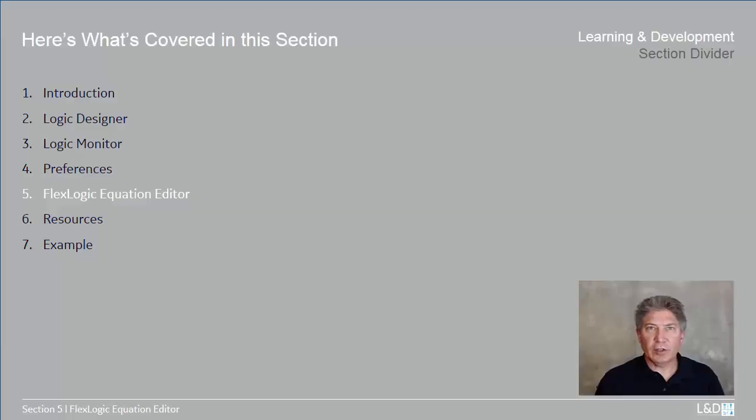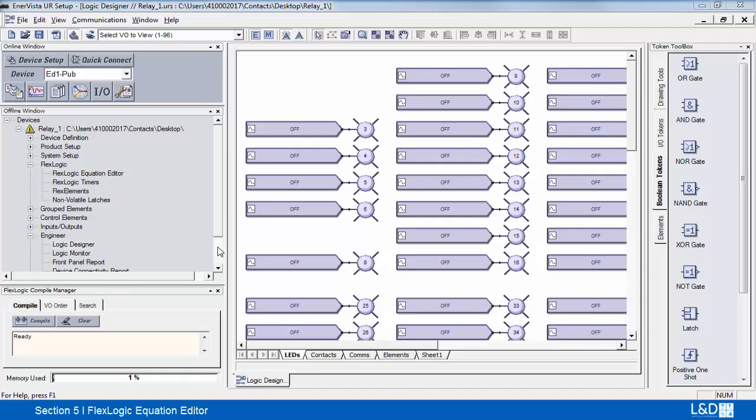In this section, we'll take a look at the FlexLogic equation editor. The FlexLogic equation editor is located under the FlexLogic section. It's available both in the offline menu and the online menu. Both the logic designer and the equation editor cannot be opened at the same time.